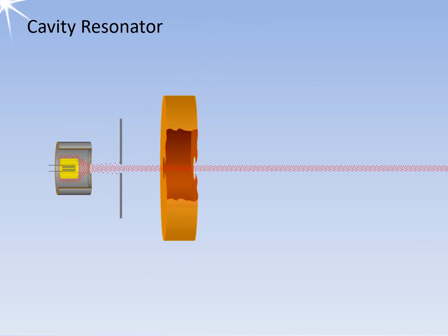A cavity resonator is now inserted, with the electron beam passing through the center hole. As long as this cavity resonator is without additional voltages, the electrons remain unaffected. This resonator is called the buncher cavity. These cavity resonators make the Klystrons highly frequency dependent. Klystrons are typically designed to operate at a single fixed frequency. The bandwidth is usually only 0.1 to 2% maximum. For Klystrons in S-band, at 2.7 to 2.8 GHz, this corresponds to a bandwidth of only about 55 MHz.